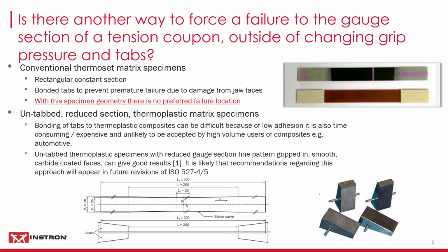Okay. Well, that is a good point. Machine misalignment, which will create bending stresses, will create stress concentrations, and depending on the type of the bending, that could actually be in the center of the specimen. And hence that's actually going to cause you to get failure in the right place. But of course, it will be failure at the wrong stress level because of the bending. So the answer is yes, but I don't think it's a desirable thing. I think you need to have good alignment.